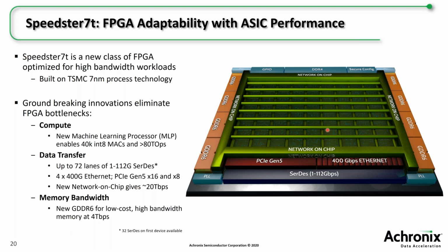And from experience, oftentimes in classic FPGA designs, you can have more than half of your logic just used to pipe stuff up, to plumb everything together. So in this case, all of those resources are offloaded into the hard network on chip, and you have much more resources available to you for doing useful processing instead.